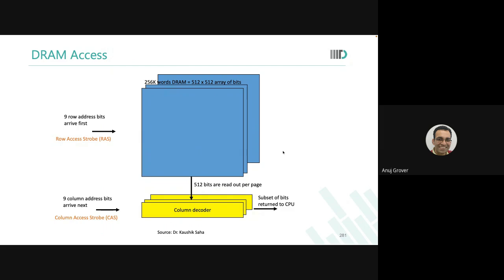I just need to change the column addresses, and I will be able to throw out lots of data to the chip. Not only that, I'm not waiting. I'm also enabling burst mode by giving CAS after RAS.